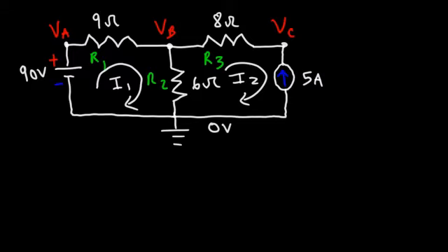Now, you need to be familiar with Kirchhoff's voltage law, which basically states that the sum of the voltages around a closed loop circuit adds up to 0. Now, you also need to be familiar with the polarity signs. For instance, as you travel around a circuit, if you go from a negative value to a positive value, the electric potential is increasing.